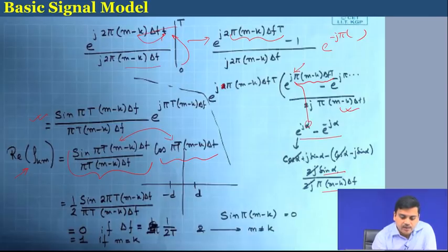So, sin A cos B, if you multiply that, you get 2 sin θ cos θ, you are going to get 2 sin θ and a half, the normalizing factor, because of this comes in the denominator. So, you get a sine of 2 times this expression, and if we set this equal to 0 to maintain the orthogonality, then what we get is that Δf, that means this particular term, should be equal to 1 upon 2T.